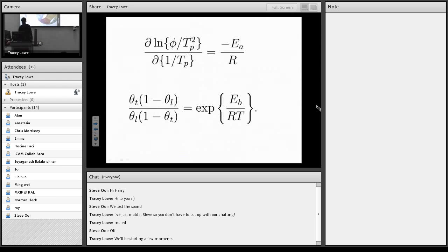One of the most common equations that's used to analyze the thermal desorption spectra is called the Kissinger equation. The Kissinger equation was originally derived for chemical reactions. So supposing I have a test tube with a pink material and it turns blue. That's what we call a first order reaction. It's happening throughout your assembly, and there's no nucleation and growth involved. So there's not one region which starts to turn blue, but the whole solution goes blue. Of course, Kissinger's original equation could be applied to any order of chemical reaction, but it is still a chemical reaction happening fairly homogeneously. So in this equation, this is the heating rate, and this is the peak temperature from your TDA curve. And from that, you get a binding energy. There's nothing in this about the shape or the size of the specimen.